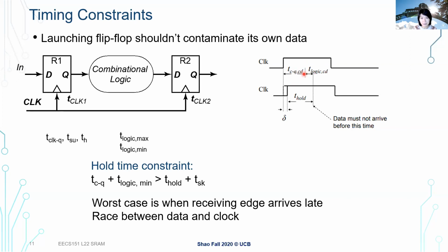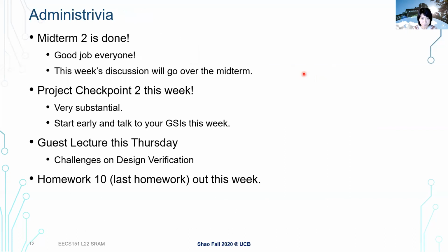So that basically wraps up our clock discussion. Any questions so far? Again, very important: we started with timing, not assuming clock non-ideality, making sure it's not only the combinational part but also the sequential part, the registers, that contribute to the delay. And then later, it's not only the delay part; the clock signal may also be non-ideal, so you also need to budget your circuit to make sure it meets those constraints.